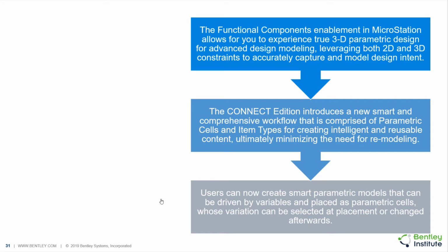Here, for example, in OpenBridge, we can say internally in the software, with a toggle, that I want to accommodate the back wall of my abutment all the way up to the top of the deck, right? And also when you place a pier and then you place bearings, the software automatically lowers the pier to make room for the bearing and the beam seats, right?